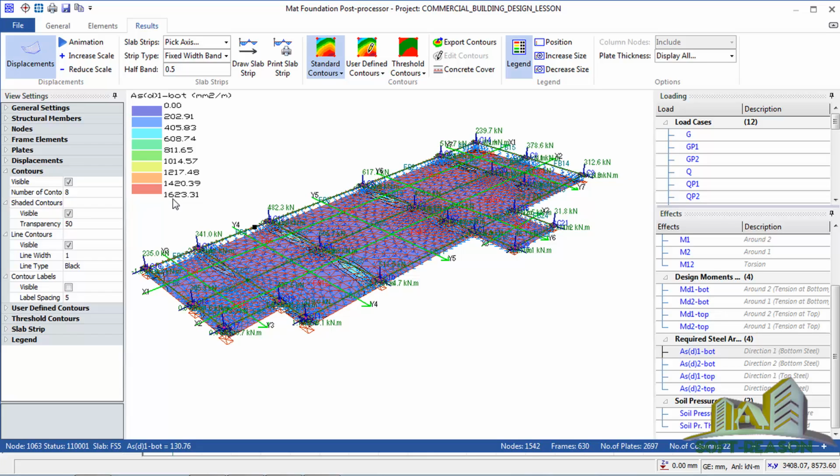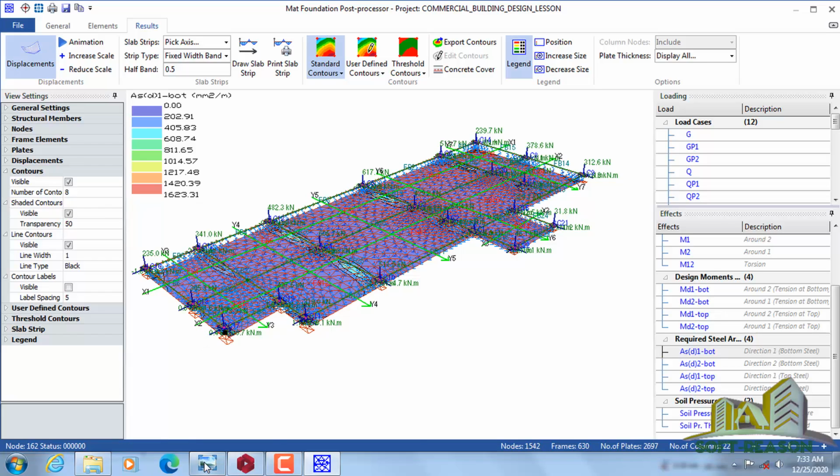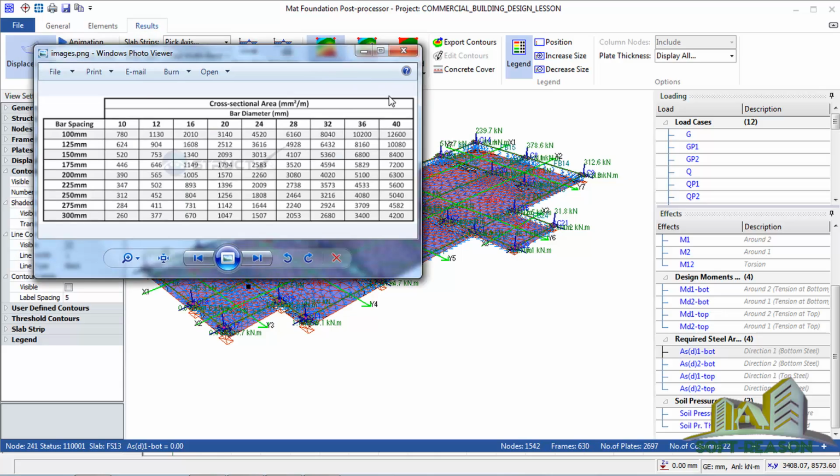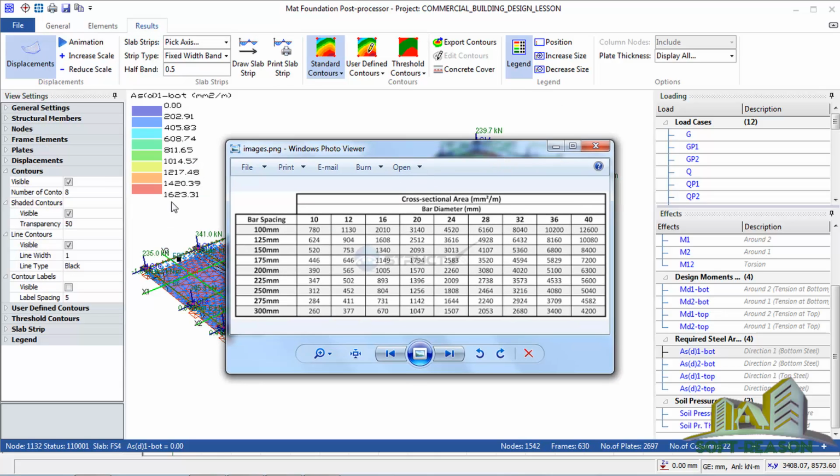And so if you use your table, you use this table. This is the area of steel, and it will depend on this spacing. So let us take our spacing to be 150. At 150, where can we find that? It is at Y20. At 150 we find that at Y20. So at 175 we find that also at Y20. Y20 to be our bottom reinforcement.